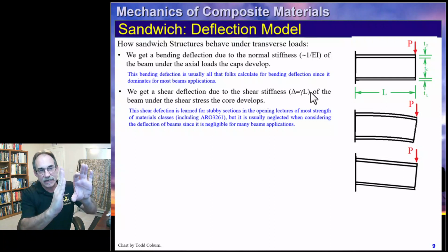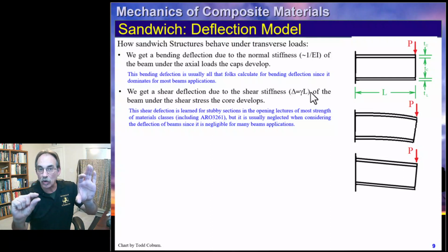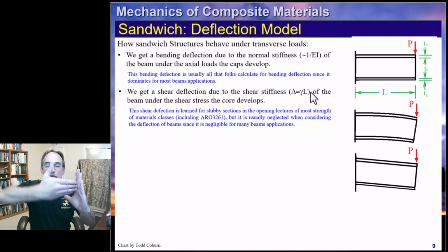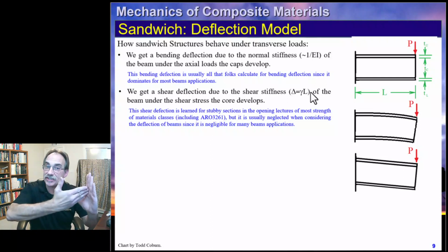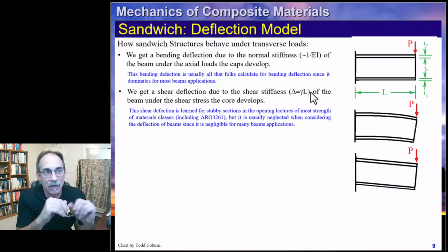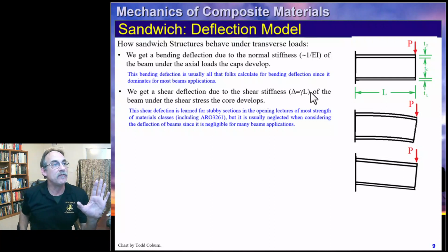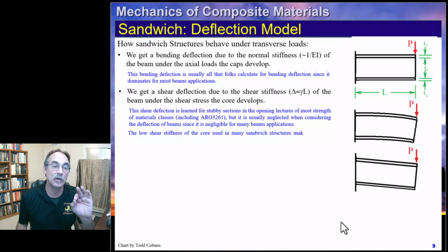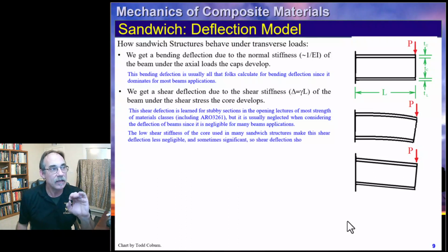That's because it's how those little strips of the beam stretch or compress, and that stretching and compressing is what causes or resists that bending. With the other case, we were looking at how the shear properties of the beam resist that motion, which gives us a rigid dropping kind of deflection. So the first one we're familiar with, the second one we've done also, but it's a little less intuitive. We kind of left it behind when we were talking about deflections.